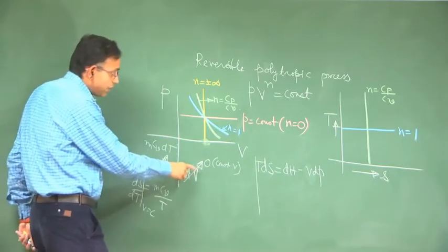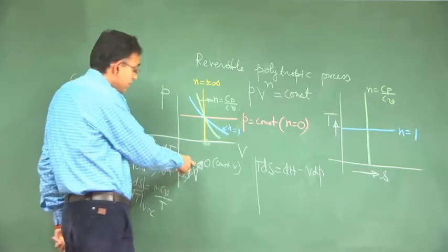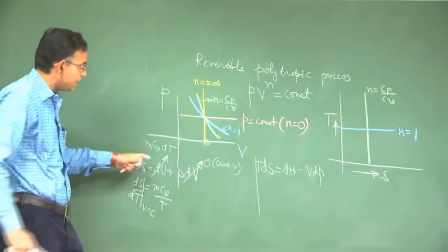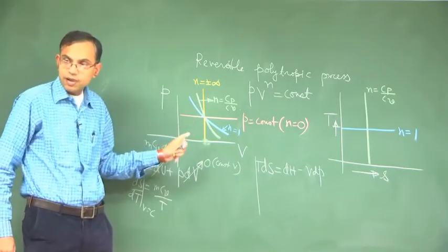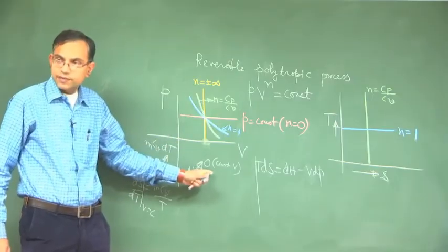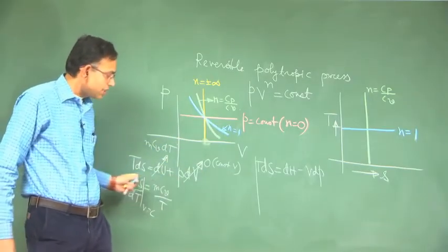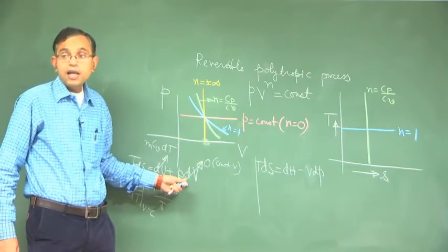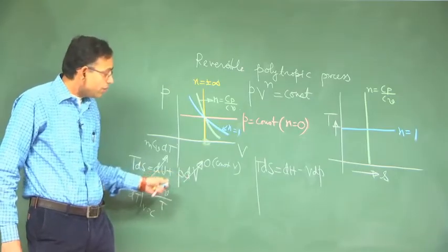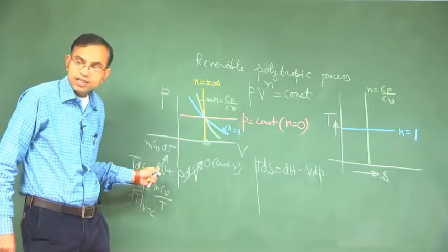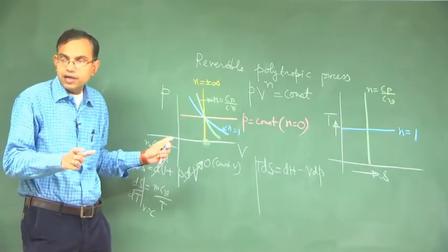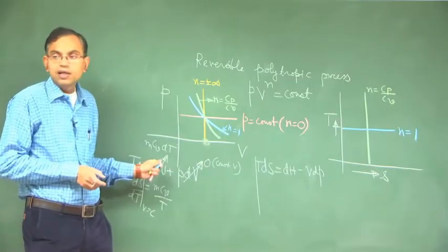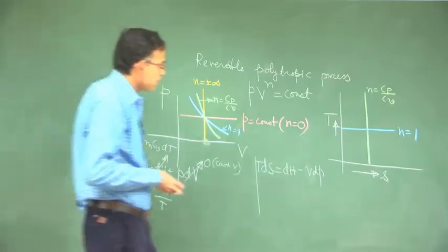Okay, so what you are saying is if the volume is constant, then it is true. If the volume is constant, then you can write du equal to mCv dT for any substance, but if the volume is not constant, so this equation we are writing for any substance and then you are applying it for a constant volume process. So, before applying it to a constant volume process, if we write this, it is better to commit that we are writing for ideal gas. If we from the beginning commit that it is constant volume process, then it can be generalized. Okay.